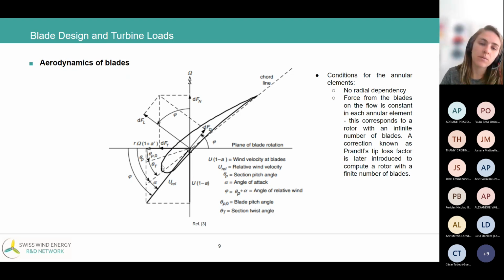So once we divide our blade, let's say into 10, 20 sections, one section will not have an influence on the next section. But of course, this is one thing that we are simplifying, because in reality our airflow will be 3D. We'll have some flow going from one section to the other, but to start simple, we use BEM and we use these definitions.